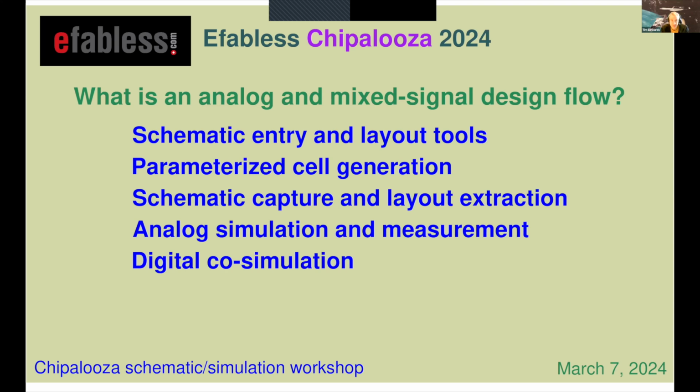I'm not going to spend much time talking about that, mainly because of all the IP blocks for the Chipalooza challenge, the vast majority of them are analog only. The only digital for them would be things like static inputs like trim bits or enable signals. You don't need digital co-simulation just to set an enable signal. The one that would likely need co-simulation is the ADC, and I may get together with the group that's doing the ADC, and we'll try to figure out how to get the digital co-simulation working right.